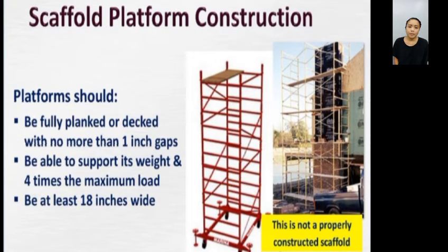Scaffold platform construction. Platform should be fully planked or decked with no more than 1 inch gaps. Be able to support its weight and 4 times the maximum load. Be at least 18 inches wide.